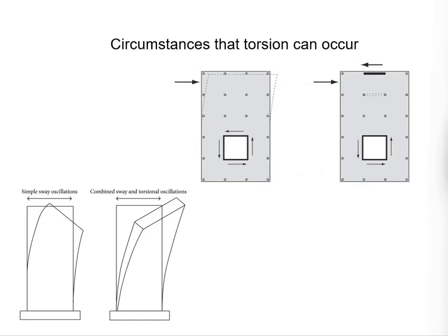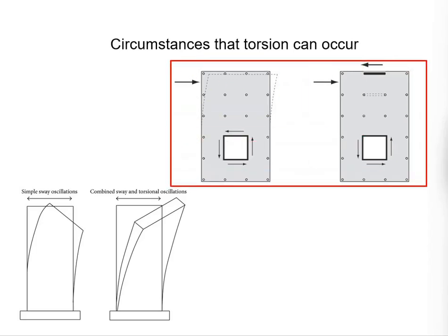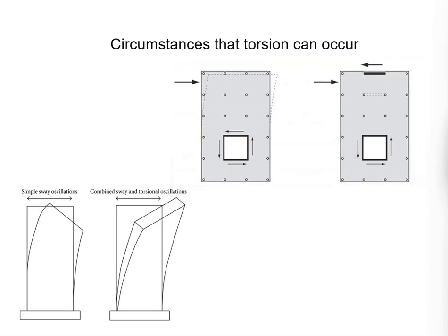This will require torsional resistance within the core wall, and the relevant columns may also be subjected to torsional forces. Now, if you strategically place the shear wall somewhere here, the resistance can be contributed by this shear wall. This will minimize the torsional effects onto the structural element. This gives us an idea of how the way you arrange the structure would influence the response of the structure.